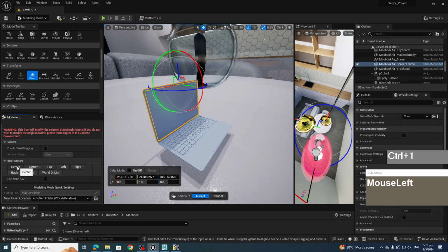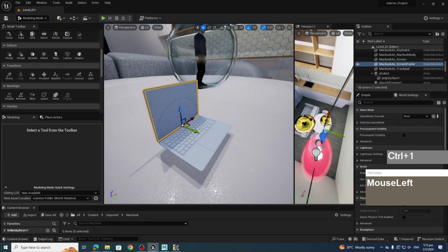The first thing you want to do is to create a sequencer. Right mouse click in the center, go to cinematics, and boom, create a sequence. Now it's at the bottom of the mesh. And this sequence, once I'm happy with it, you go over to the bottom of the 3D view, right mouse click and rename here, or press F2 and say accept. I'm going to call this my master sequence.